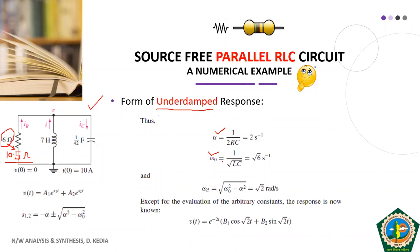So if you do that, your alpha will come out to be 2 and your omega naught will come out to be under the root 6. Okay, and here you can easily see that your omega naught term is greater than your alpha term. So that's why we get an underdamped response, and from the value of alpha and omega naught we calculate omega d. Omega d comes out to be under the root 2 radian per second.